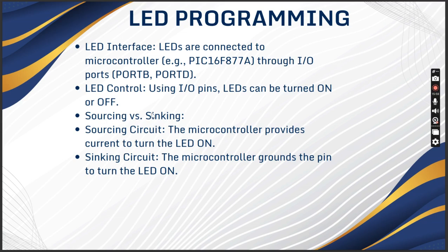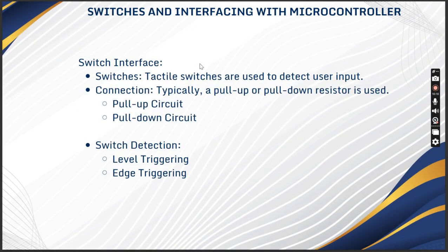Next, sourcing versus sinking. What do you mean by a sourcing circuit? That is nothing but the microcontroller provides the current to turn the LED on. A sinking circuit is nothing but the microcontroller grounds the pin to turn the LED on. Okay, next we go through the switches and their interfacing with the microcontroller.